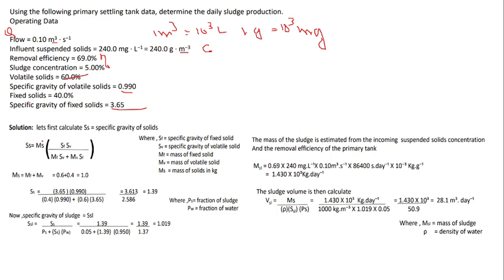We are going to use the same relation to find the specific gravity of solid. We know the relation. 100 is the assumed weight of the solid, right? So the weight of the solid is kept here as Ms, which is the mass of the solid. We generally assume it as 100, but instead we are keeping it as Ms in the formula here.